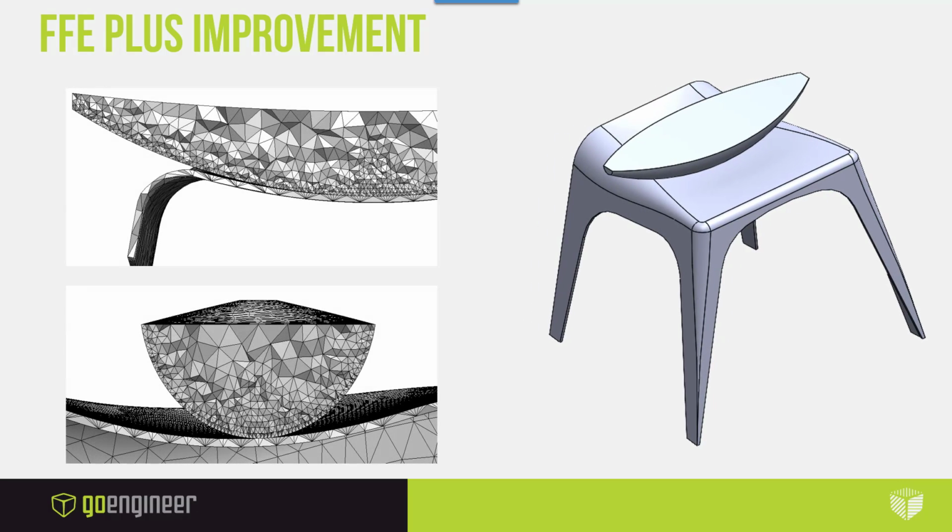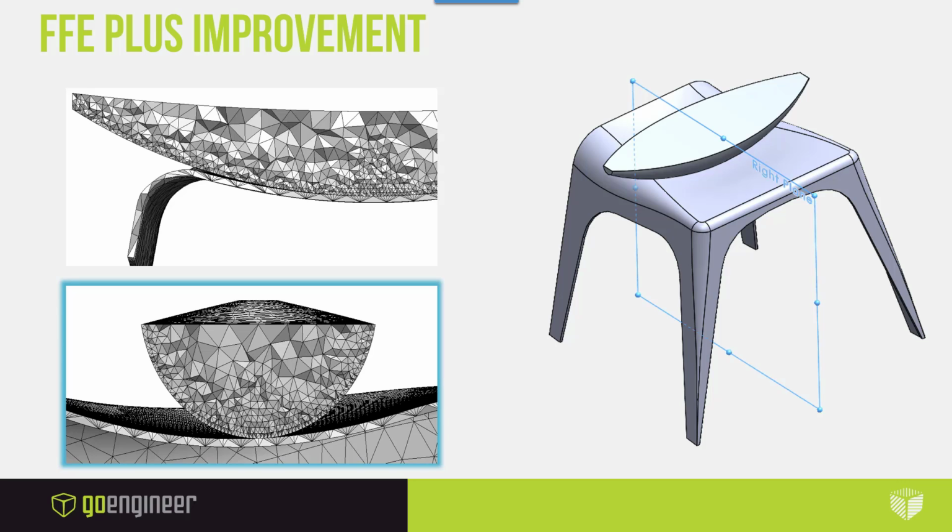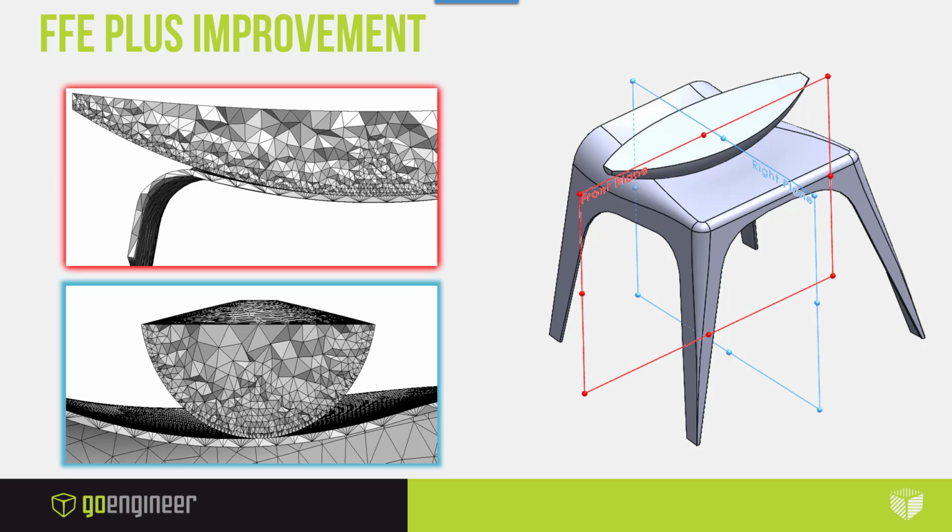So just to give you a better idea of how the contact was set up, the no penetration contact here can be seen on the right plane slide on the bottom. We have a pretty high density mesh in there. On the front plane, which is the section B on top, you can see that quite a bit of that mass on top, which was said to be aluminum, was actually making contact. So to test this out, what we did is we set up some fixtures on the feet, just turned on gravity, added friction of 0.05, and did not restrain that mass on top. And we just let the FFE Plus solver run.